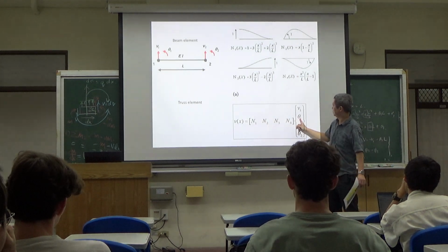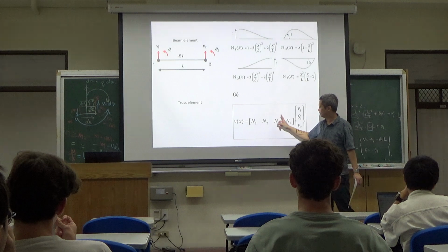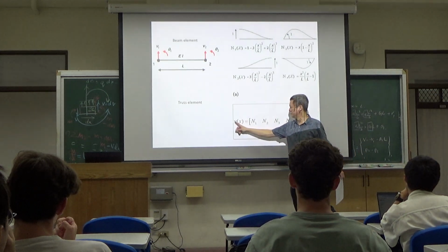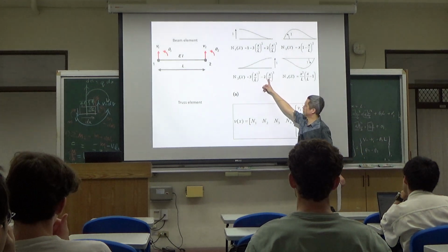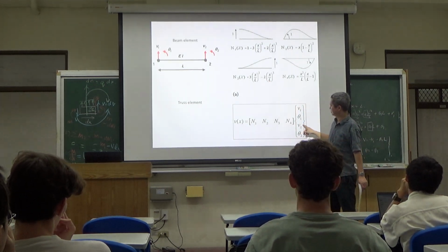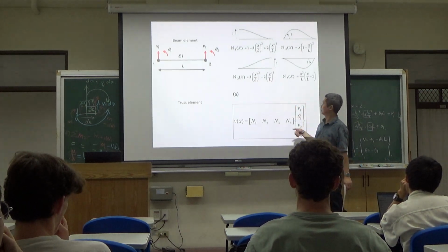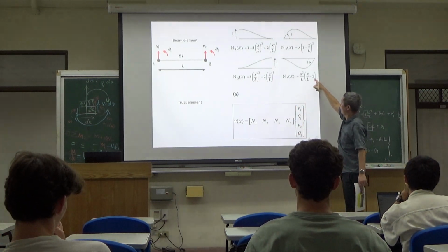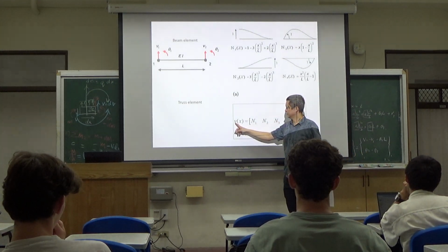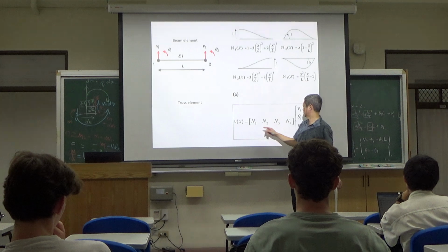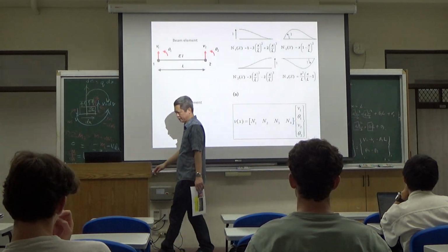Because these two associations are only non-zero when you take dv/dx. And then likewise, N3 is vertical displacement. It is 1 when x equals L. But N4 is 1 at x equal to L when you take the gradient dv/dx equal to theta 2.